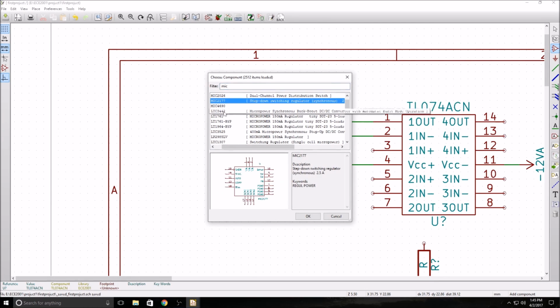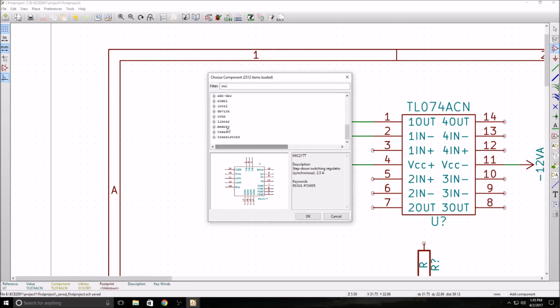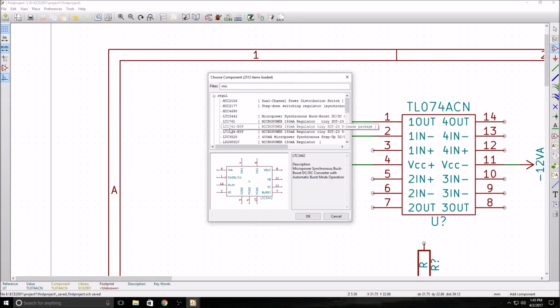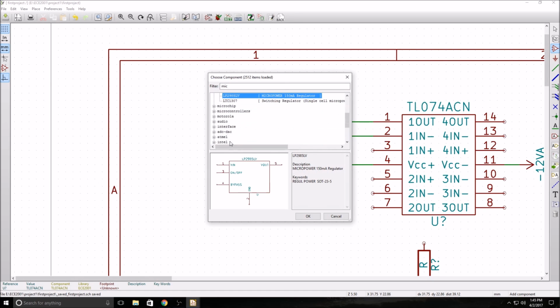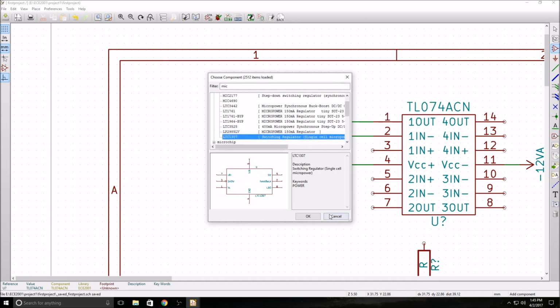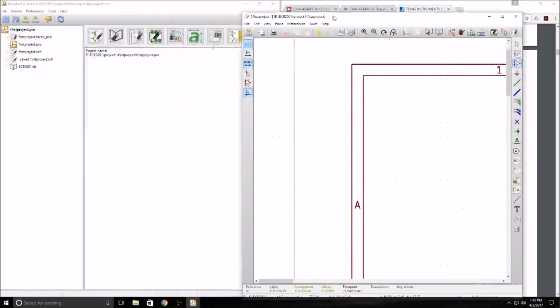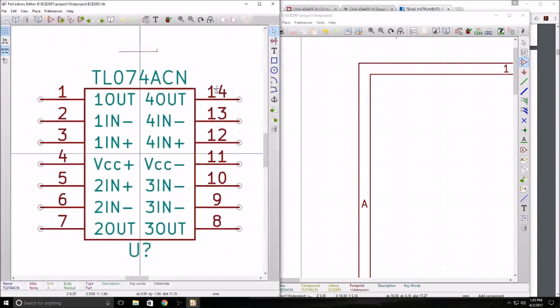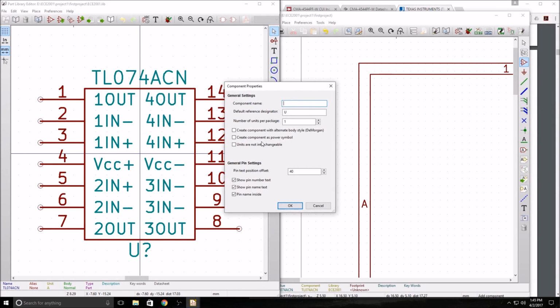And let's see if they have any microphones that are two terminals, because that's the one similar to the one that we're using. It doesn't seem like there is any, so we should make our own microphone too. So we'll go back to the schematic library editor. I go over and I say I want to create a new component. I'll just call it mic. Hit OK.